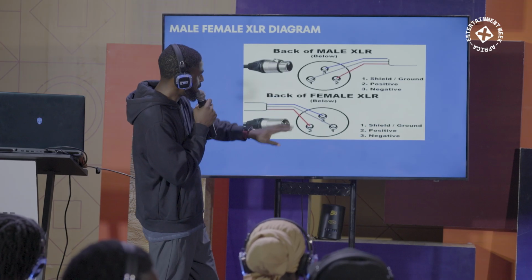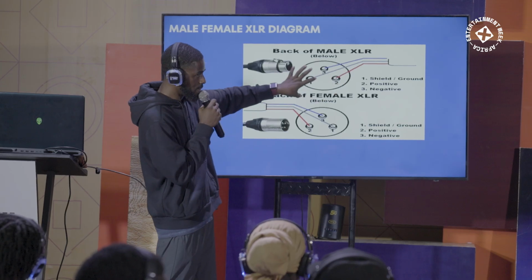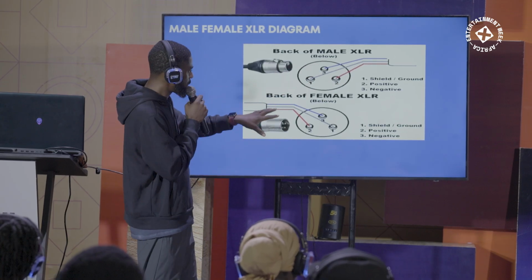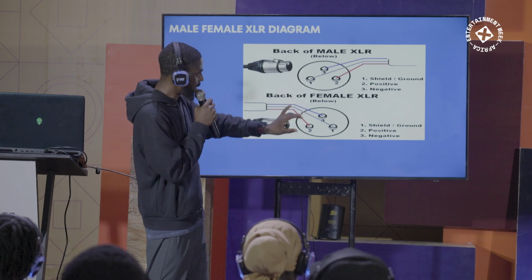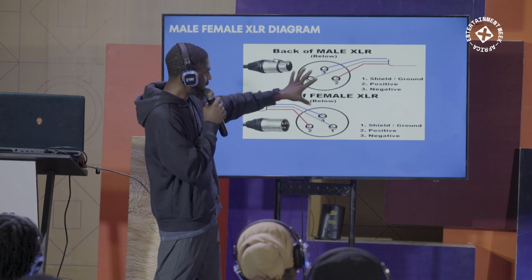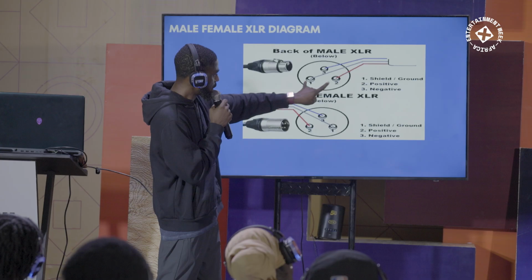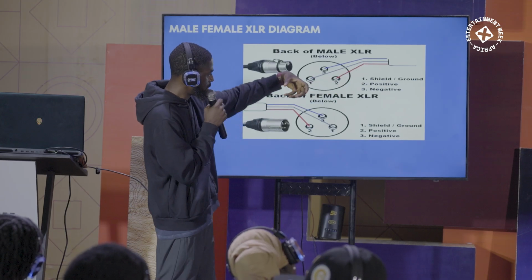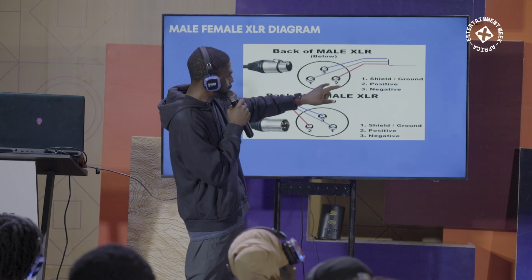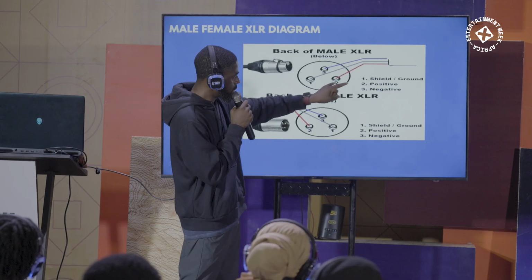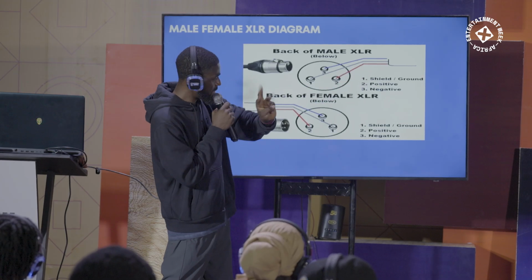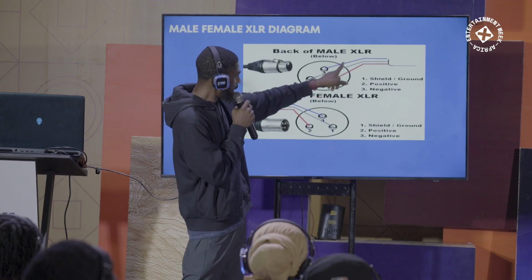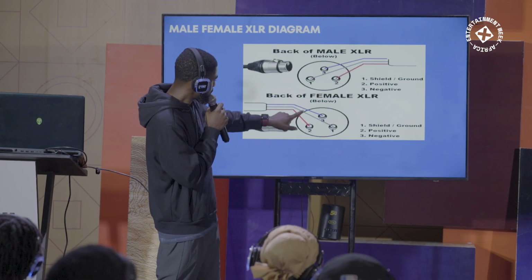So it means that when you're soldering, you guys understand the word soldering, right? When you're soldering a microphone cable, it's important for you to take into consideration the connector's ports. How do you want to solder? Like this diagram has given to you, for most of the microphone cables you see that there are color codes on the cables. There are always 3: red, white, and blue.